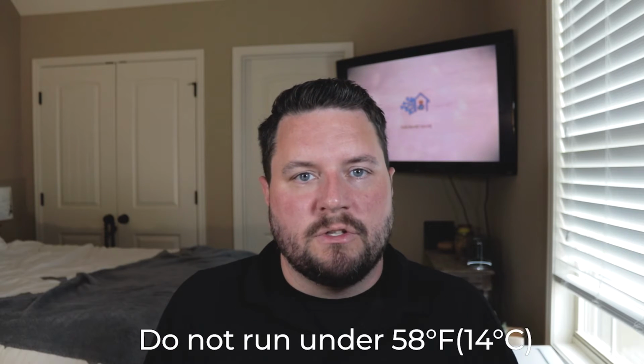Is the outside temperature too cold? Say it's 50 degrees Fahrenheit outside and you're trying to cool your house down. If you don't have a big enough heat load outside, the heat exchange won't work and the inside unit will freeze up. If it happens to be a cold night outside, but you've got your house closed up and it's hot inside the house, open some windows up if you can.